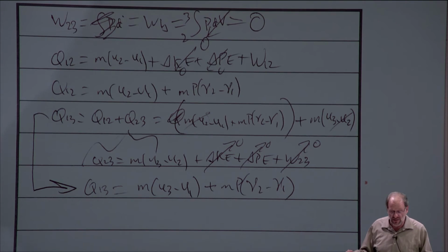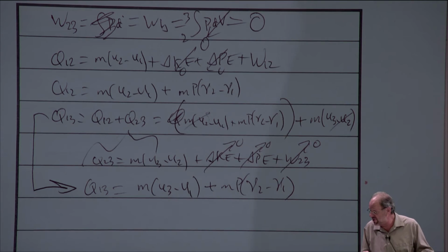Okay, what about state point 2? Yes, right, we know that the pressure at 1 and 2 are the same. We have the pressure and we know it's a saturated liquid. So state point 2 is known. We have VF, we have UF if we need it, although we don't need it.